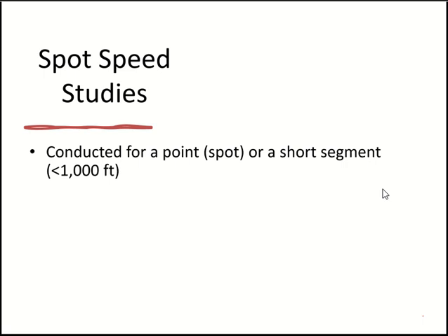It will not be a point, but they have given us some margin that if your distance is under this limit, you can still consider it spot speed. Clear? So spot speed should be over a point, but if you don't have the detector to measure over a point, you can do distance upon time, but the distance should be under this limit. Clear?